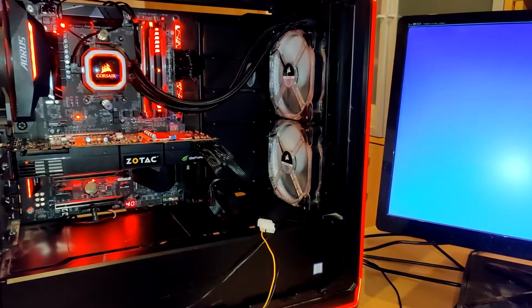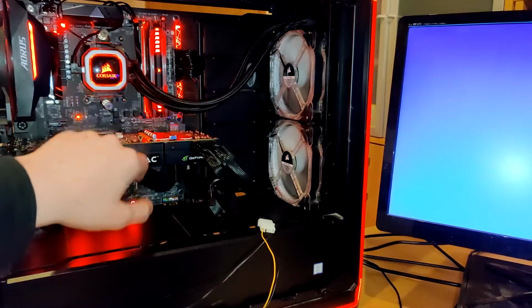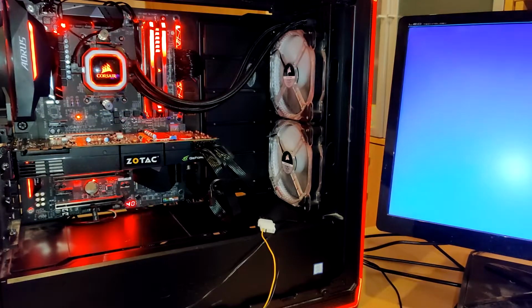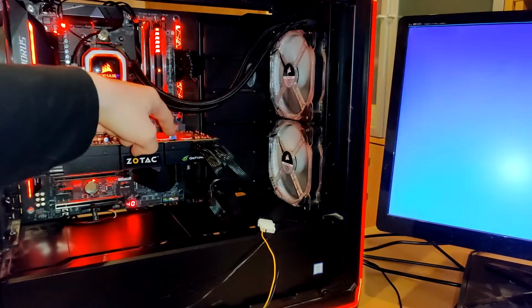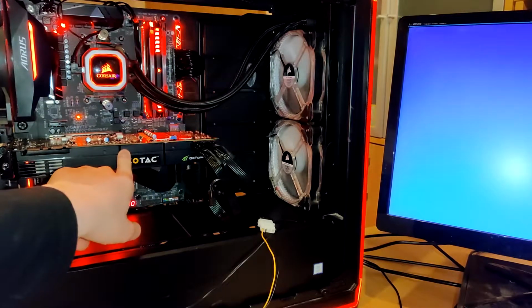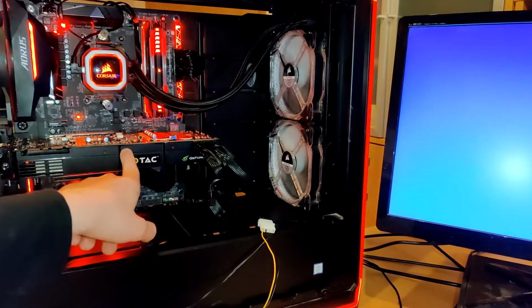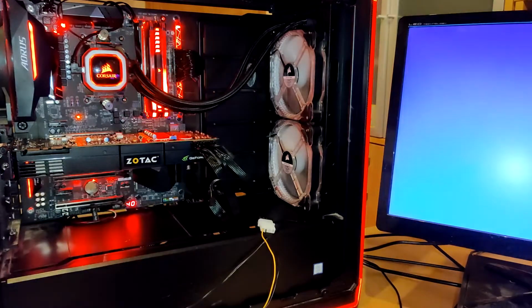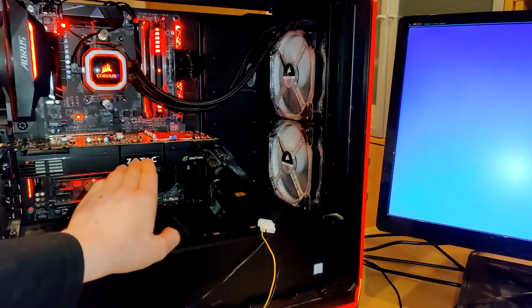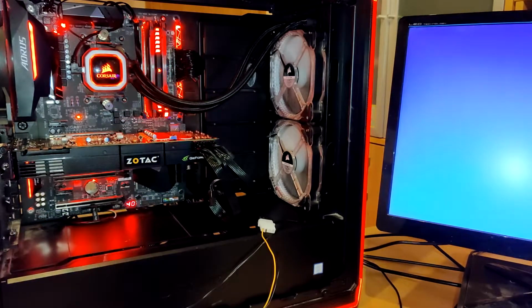And yeah, there you have it. You can see all these capacitors, all the extra capacitance that we have put on the VRM, which does help keep up the minimum voltage. We have a potentiometer right here. Actually, that's not doing anything. I've deactivated the volt mod for this, because that volt mod is for the memory, and Hynix memory does not like to be overvolted. So that's not doing anything, but the capacitors are helping the card, the core and the memory, to keep the minimum voltage up.